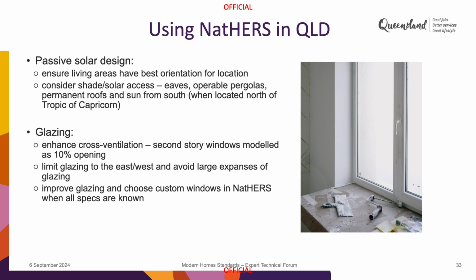The other really important aspect is the glazing. The more ventilation that you can create, so the higher the opening of the window, the better the rating will be in the NatHERS scheme. That means selecting a custom window from the expanded window library in NatHERS will improve your thermal star rating. Now, currently, most of the NatHERS tools have included the WERS custom and default library windows, so you'll see those benefits in the thermal star ratings.